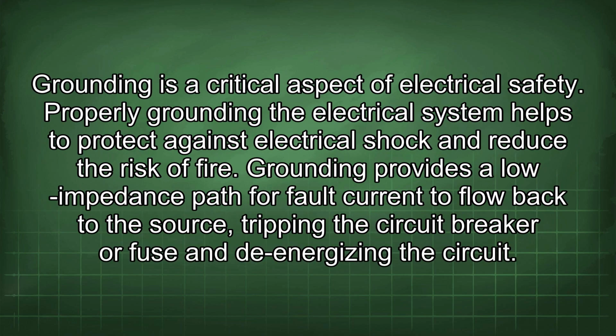Grounding is a critical aspect of electrical safety. Properly grounding the electrical system helps to protect against electrical shock and reduce the risk of fire. Grounding provides a low impedance path for fault current to flow back to the source, tripping the circuit breaker or fuse and de-energizing the circuit.